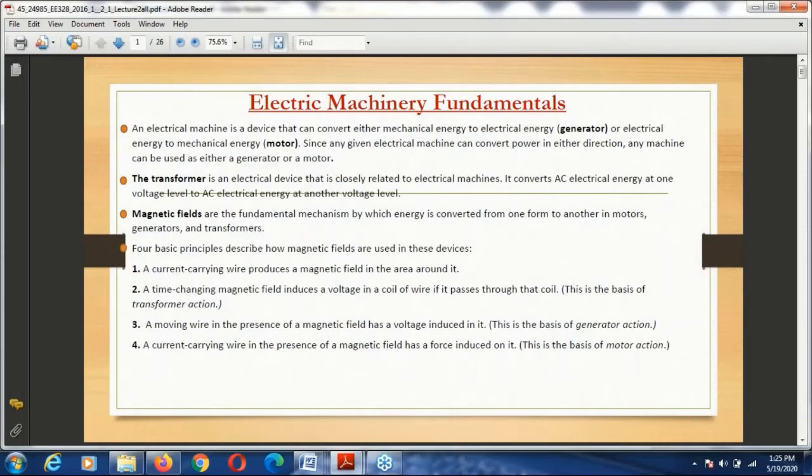So now you have the N turns, then the cross-sectional area, then the mean path length. So you have an analogy between magnetic and electric circuits. Now, in an electric circuit, you have the resistance. You know this one from before: current is voltage over resistance. Electric circuits can either be in series or in parallel. You should know those from your electricity lessons in secondary school. When they are in series, you calculate the resistance differently, and when they are in parallel, you calculate the resistance differently.